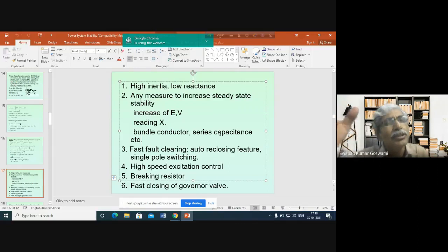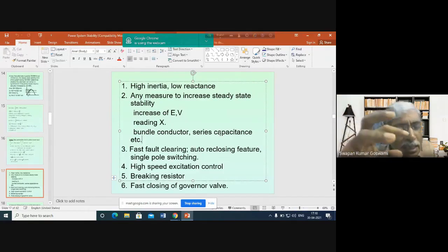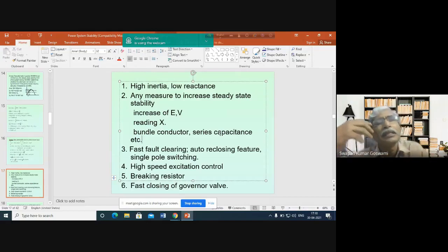So the subharmonic current may create resonance in the system, and if that subharmonic oscillation matches the natural frequency of oscillation of any of the rotating parts of the system, including the exciter, generator, shaft, and turbine, then this may cause great damage to the generator, turbine, and exciter.